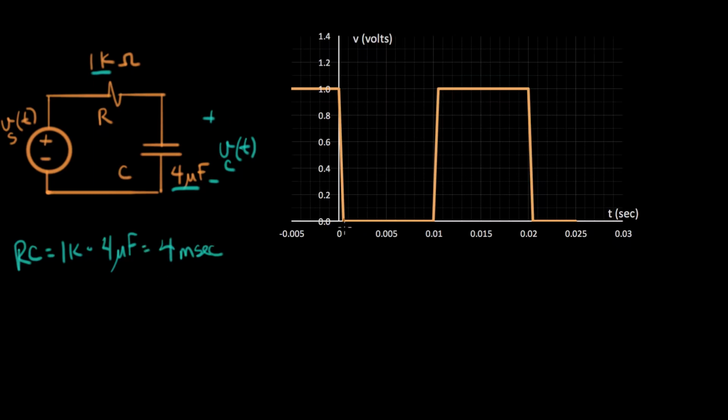That means I know that that straight line sketch, here's 5 milliseconds. It goes through right about here. I start up here. I can sketch in a straight line like that. It goes roughly like that. Same thing over here. I can go out another 4 milliseconds, up like that, and sketch in my slope. And we'll do the third one over here. Here's 4 milliseconds after the change, right about there. And I sketch the line in.